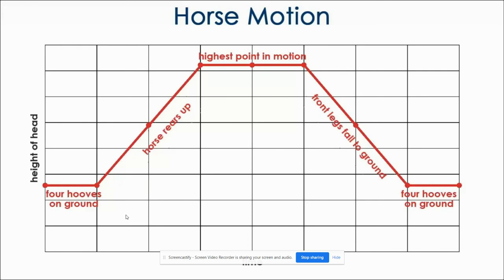Notice that the horizontal axis of this motion graph is time. But if we wanted to create a cam to create this motion repetitively as we turned a crank, we could use the same graph shape, but use cam rotation as the independent variable.